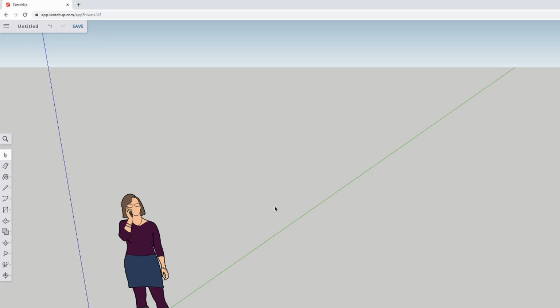The first one is the pointer icon, and this is used to select items that you want to interact with. I tend to reference this as the default element. I find it helpful that when transitioning from piece to piece, sometimes SketchUp doesn't release things very well. So being able to click off screen, or in some cases hitting the escape key, is very helpful.